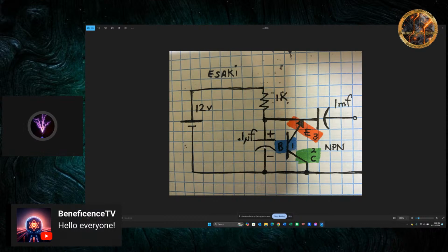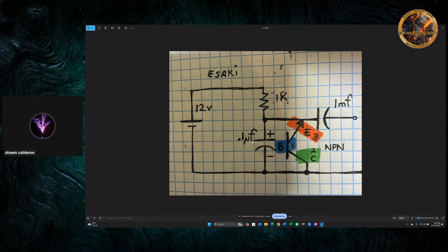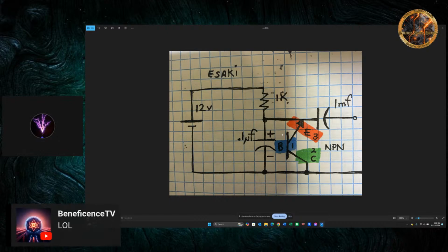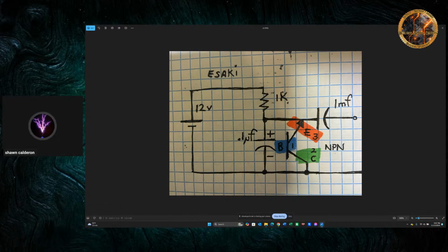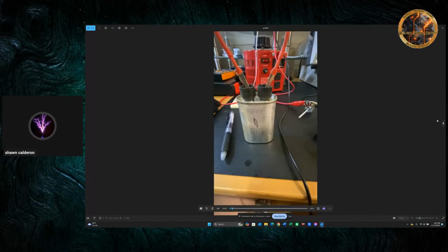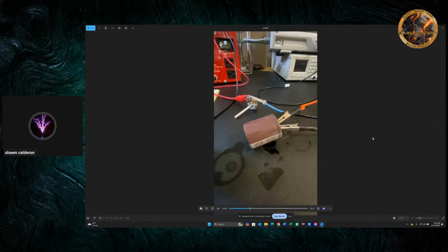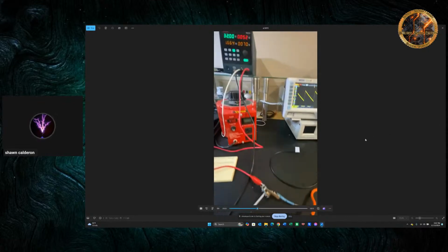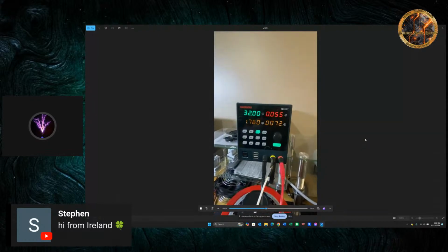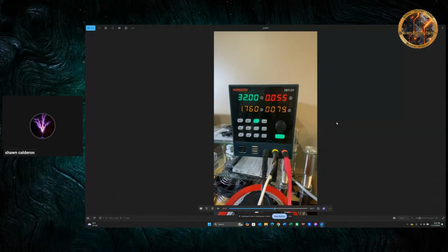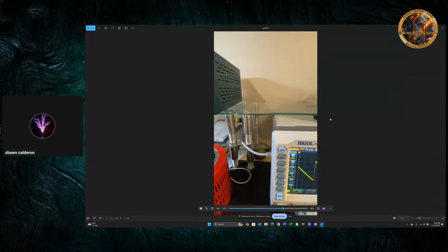The smaller the capacitor, the quicker the burst. What that means is the output is going to either have these long ramping sawtooth waves or these really tall, pointy, quick dropping sawtooth waves. That's just basically how that circuit works. I put it together with a microwave transformer, some old potentiometer, all the stuff that came out of my junk bin from the thrift store. I'm putting in 32 volts because these things have ultra low current.